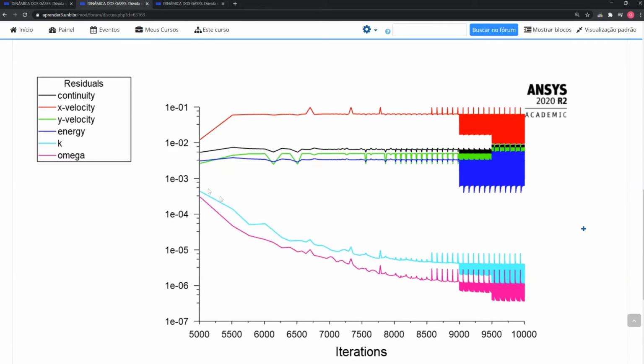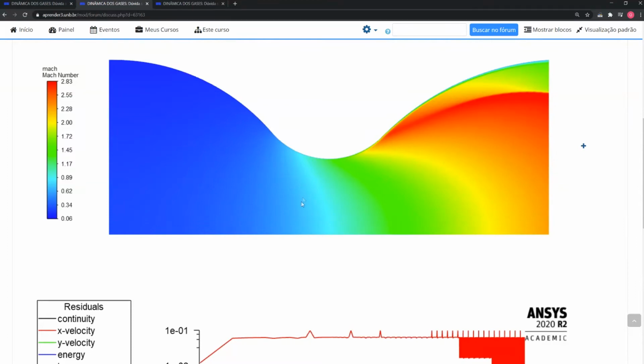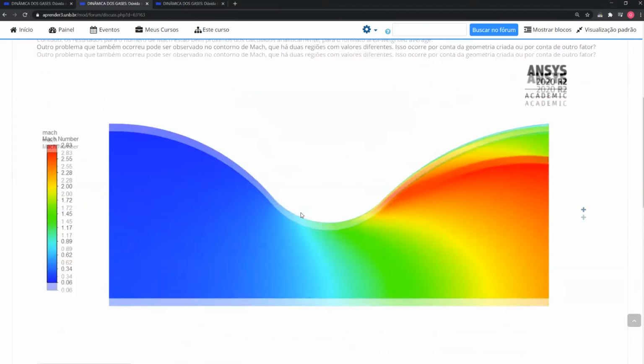K and omega parameters converge faster because of the physics of the model, right? The viscosity terms have some dissipation member in the equation, and because of the dissipation, these mathematical oscillations for the turbulence model are dissipated, they are reduced from one step to another. It's a process. Probably in this calculation you have also used a high order of simulation. Maybe it was second or third order. Just let me know which.